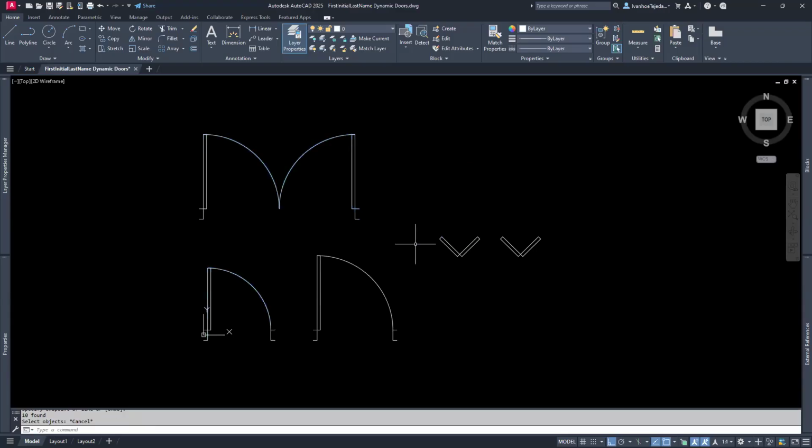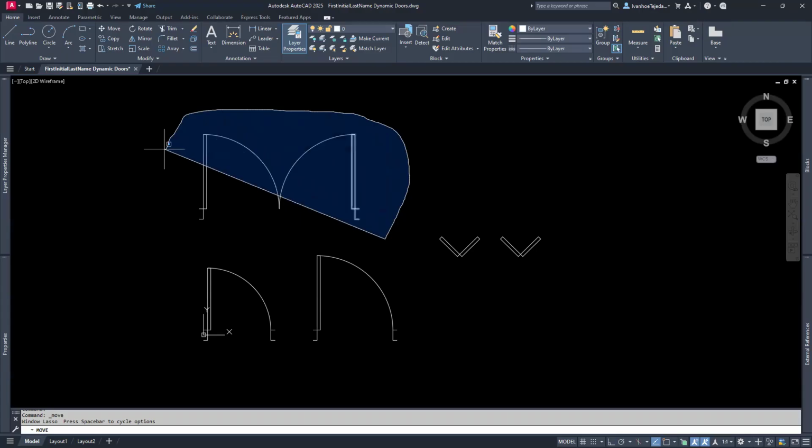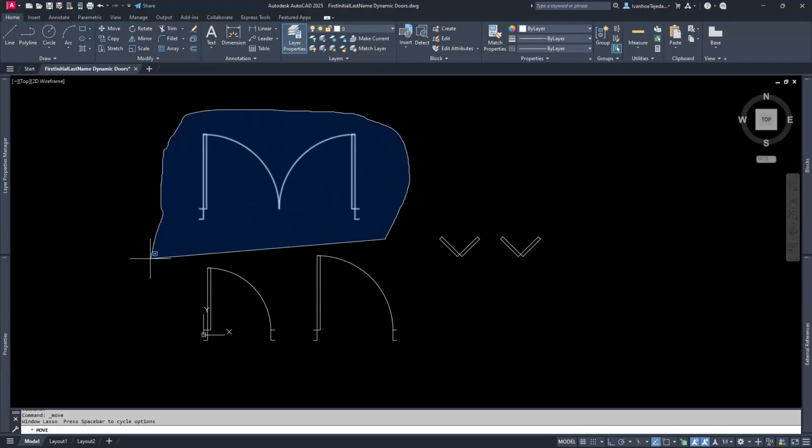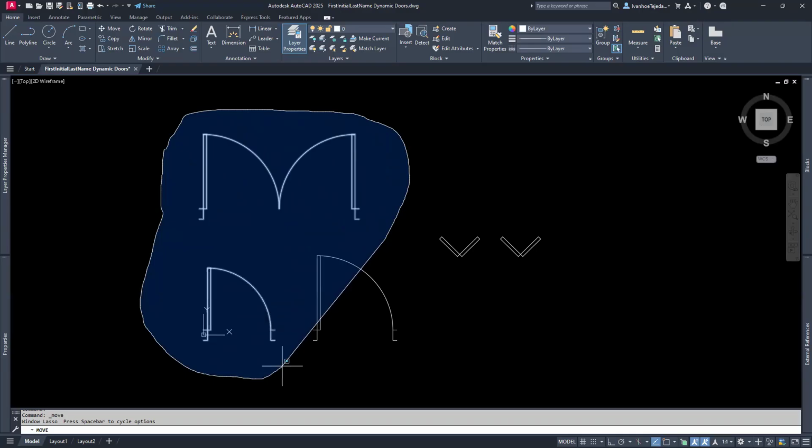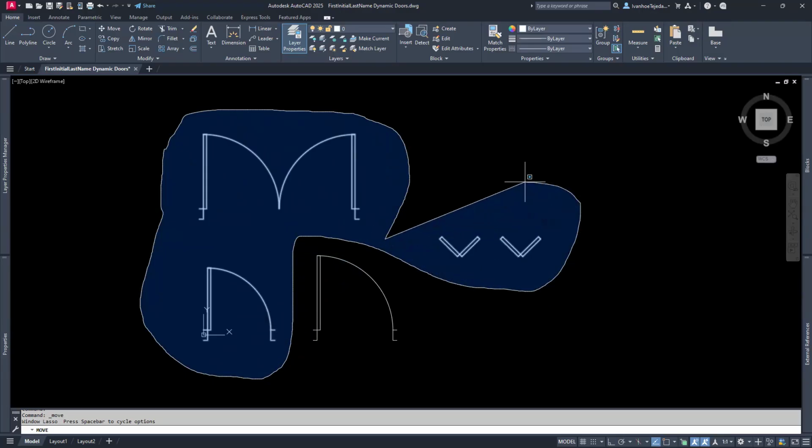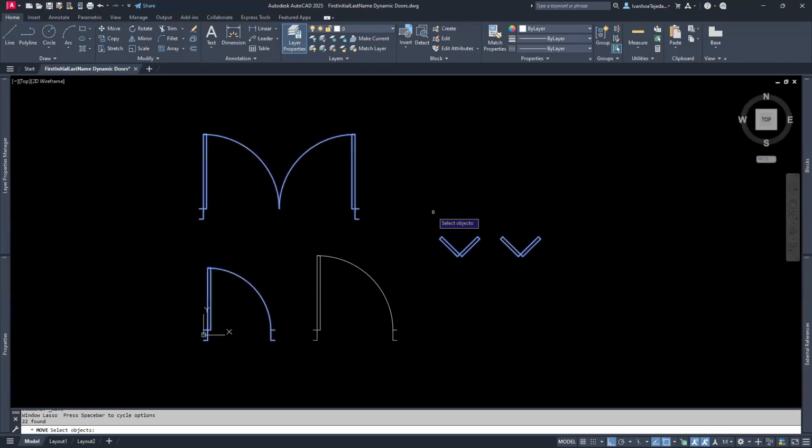And then the other option here is pick one of the commands. I'll pick move again. And this time, instead of clicking on an object, instead of just clicking and moving the mouse, I'm going to click and drag. When I click and drag, it starts to create this shape. And depending on the direction I go, I'm going to get either a window or a crossing window. And this is the one that's really helpful. And I can do this, and here I can bring it back in this direction. So I can do some really interesting shapes and select all these objects,